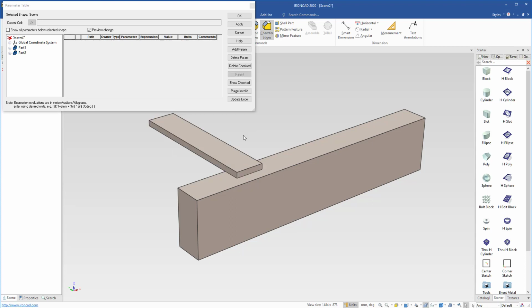So basically both of those are set up, and you'll notice when that happens, I didn't show it in the other one, but notice that the handle changed from these red or yellow colors to a blue color. It's basically indicating that it's being driven by something, so it's parametrically driven in this case. So if you try to pull this, it'll tell you you're going to break a parameter, but in our case we don't want to pull it. We're just going to use this to be driven by something else later. So now that we have this, let's go ahead and just close this for now.